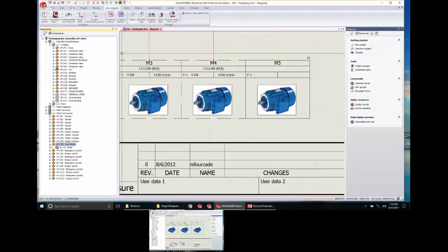If I click underneath that, you can see what symbols are associated with that component and where they're at. 04 is the fourth sheet, the 10th column. I had to think about it because I almost always say row, but it's column. We'll get into that a little bit later. You don't have to navigate that; I'll show you an easy way to go through your project. Okay, now what's missing from that M5 symbol that's on the other symbol?